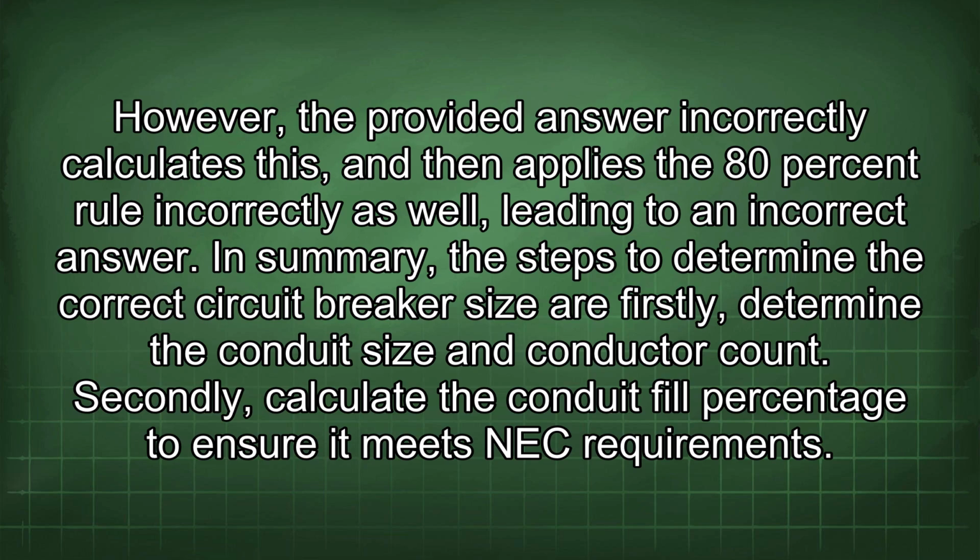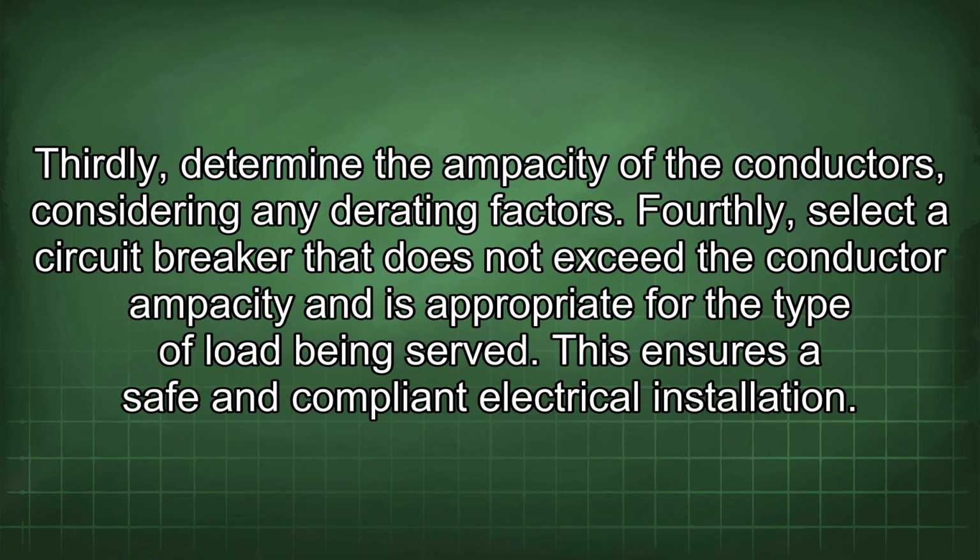count. Secondly, calculate the conduit fill percentage to ensure it meets NEC requirements. Thirdly, determine the ampacity of the conductors, considering any derating factors. Fourthly, select a circuit breaker that does not exceed the conductor ampacity and is appropriate for the type of load being served. This ensures a safe and compliant electrical installation.